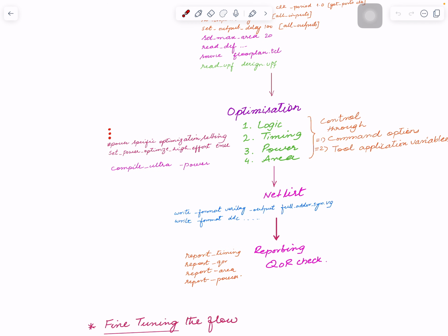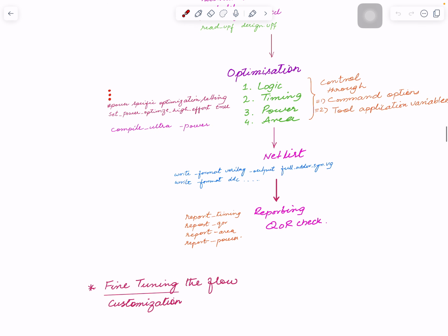But sometimes for timing analysis, if you want to do it, and we will look into STA separately later on too, you need a Verilog netlist. And for the formal equivalence tool, you need a netlist. So there are some tools which really need a netlist, so that you can save it internally. So saving a database and taking a snapshot is super important. And then now you have an optimized netlist.